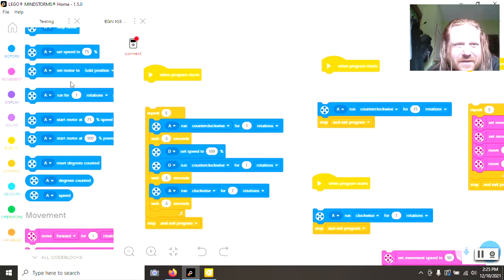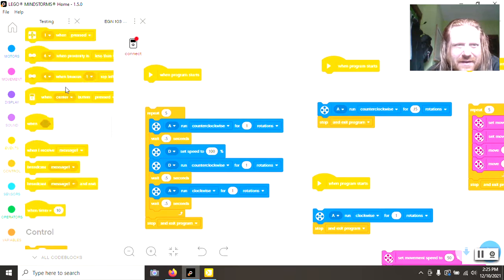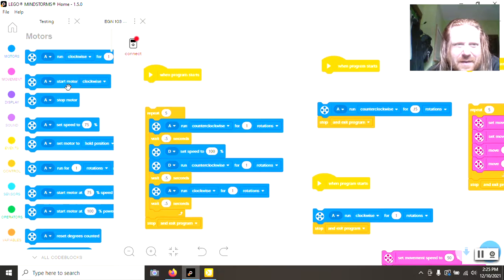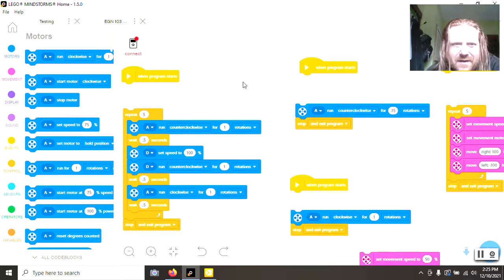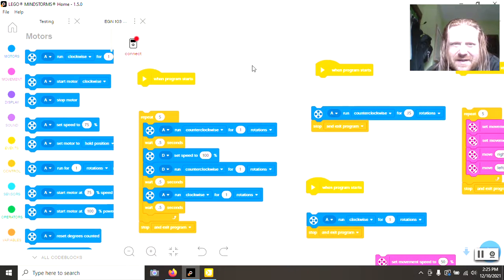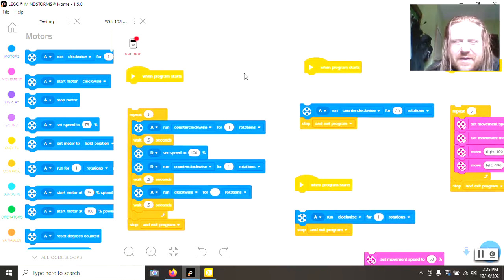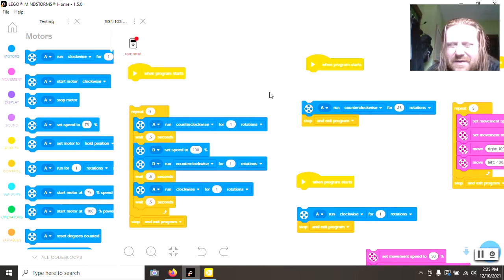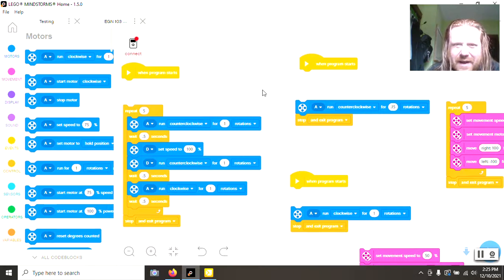But I am going to show you today what we did to program our bot, and hopefully this might be insightful for technicians and engineers of the present and future. So this one here, as you can see, is testing, and I also used it to calibrate the machine before deploying it, because in travel sometimes you might skip a tooth on a gear or something like that, or it shakes around, so you have to recalibrate it.